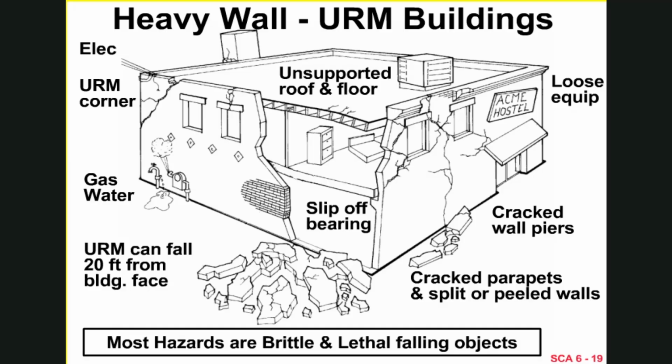The other thing that happens is that as the building tries to act like a box, as the loads are generated in the roof structure, the roof structure plane, if you will, tries to resist the forces, and it finds the corners usually as the hard point of its resistance and will tend to knock the diagonal corners out. You can see in the upper left depiction there of the diagonal corner being badly cracked and possibly being knocked off. And I'm going to show some slides of that.